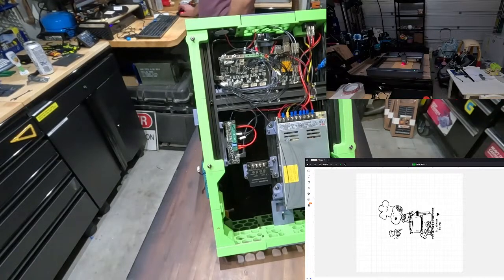Turn that off. Alright, so here what we're going to do is that recommended setting from the other user is going to be engrave, user defined, set easy panel, and we're going to go 100 millimeters a second, and our power is going to be 90, bitmap mode grayscale. That's fine. We're just going to run with it. Make sure that's set. So 90, 100 millimeters a second, bidirectional. Okay.